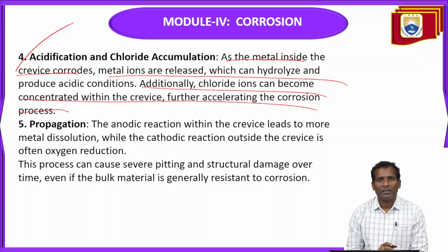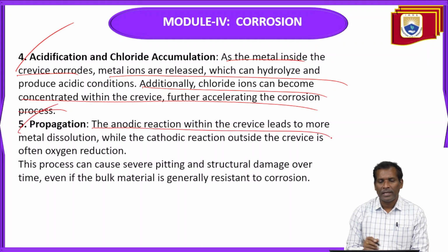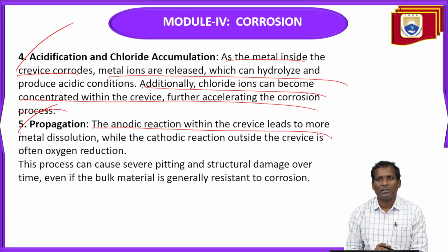So propagation. The anodic reaction within the crevice leads to more metal dissolution, while the cathodic reaction outside the crevice is often oxygen reduction. This process can cause severe pitting and structural damage over time, even if the bulk material is generally resistant to corrosion.